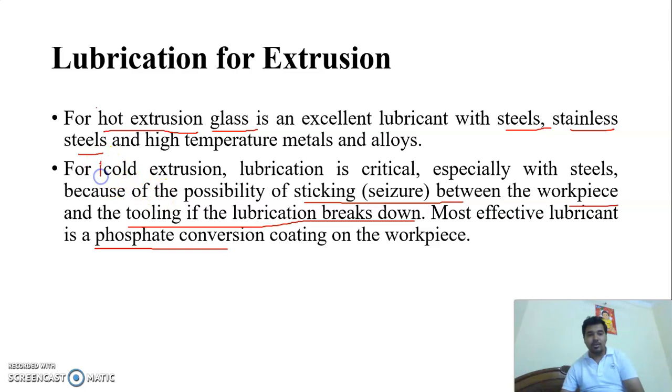In cold extrusion, lubrication is crucial and very critical, because if we use the cold extrusion process on brittle material, then there is a possibility of cracks. Therefore, lubrication is critical in cold extrusion, and so in cold extrusion we use phosphate as the lubrication.